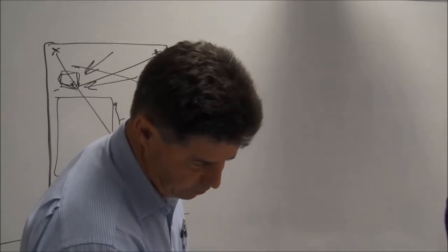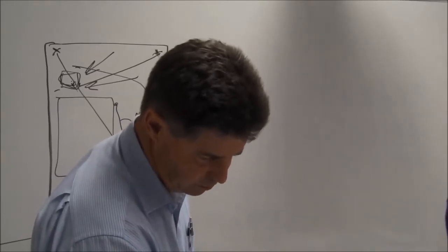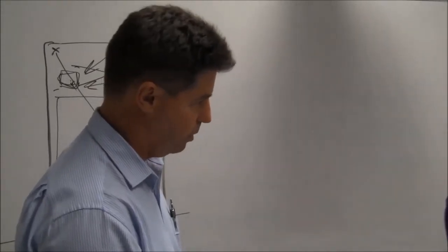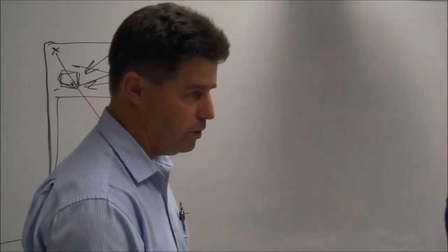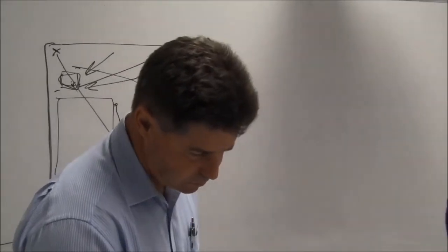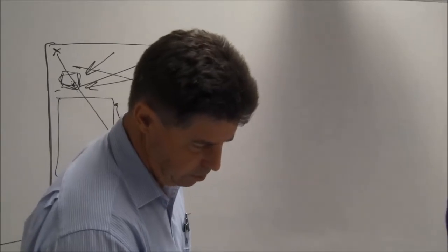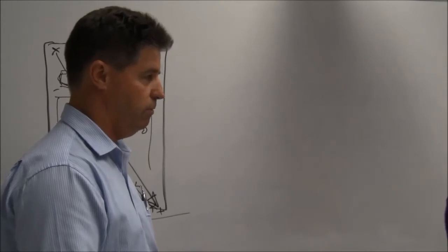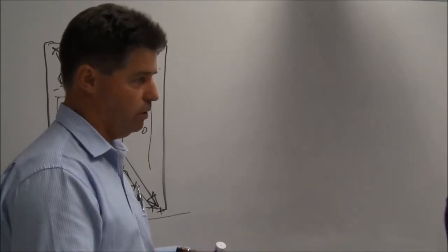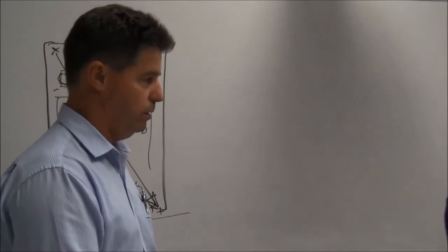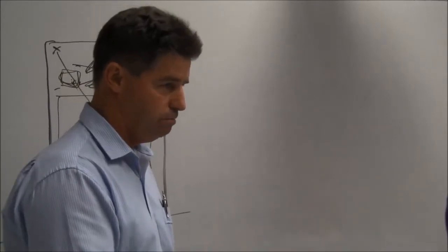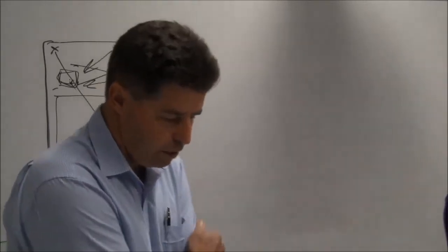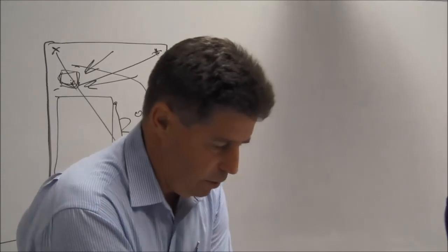The example I've given you there is, if we had a certain point, 10 minutes is going to be the time for that particular slope. Obviously, the steeper the slope, the faster the runoff, and just in reverse. So for that example, our time is 14 minutes. The rain intensity would have to be falling for a period of 14 minutes across the entire site before all of that rain gathered to flood the outlet or reach the capacity of the site.